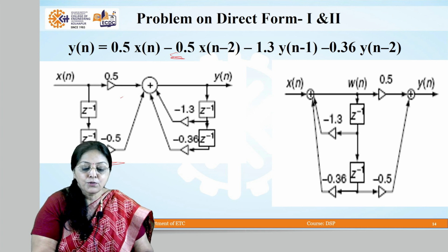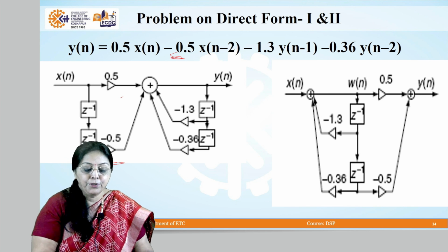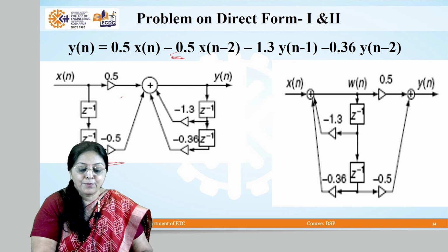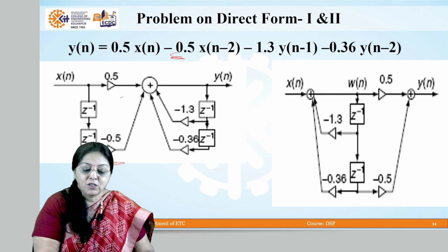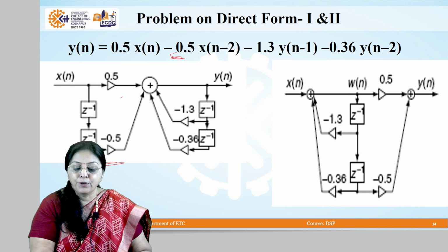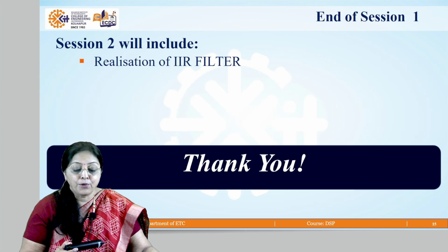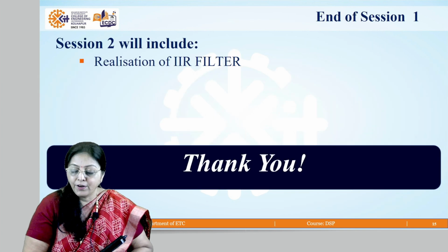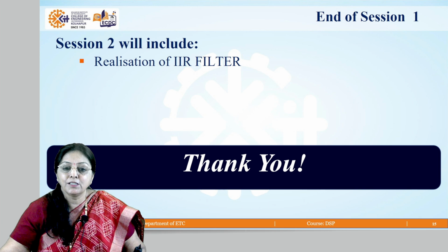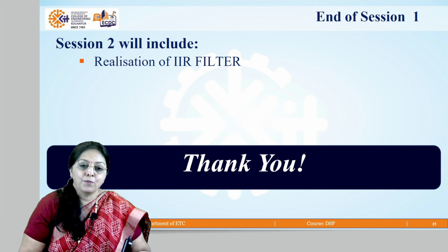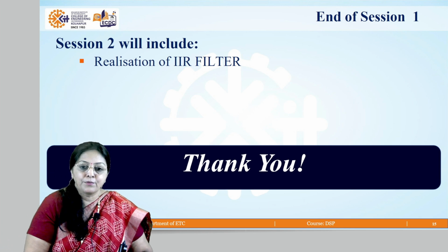Okay. So this is the direct form 1 realization, and in direct form 2 the only difference is that we use common delays instead of separate delays. For x(n-2) we would require 2 delays, and for y(n-2) we would also require 2 delays. Again I repeat, in direct form 2 realization we minimize the components for IIR system design, and direct form 1 is very straightforward.